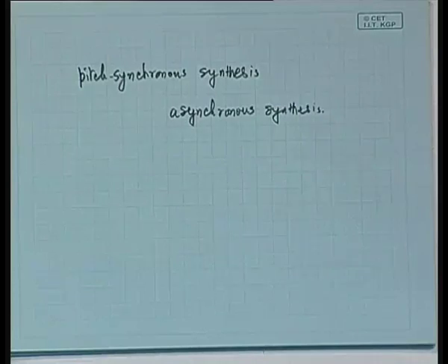Now we also show how the LPC can be used for a very good pitch period estimation, because again the success of the speech synthesis is really dependent upon how accurate your pitch period estimation is.